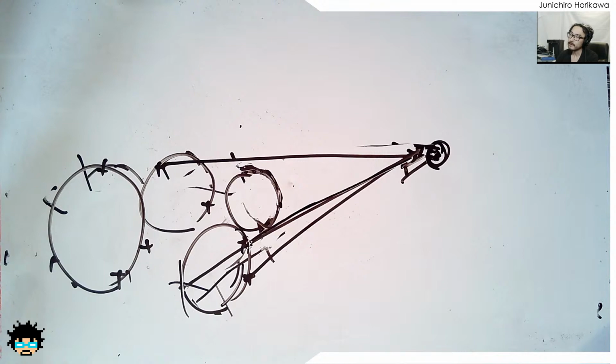Crack transform, 0, 0, which is going to be the order of the rotation and the order of the translation, scaling, and rotation. I'm going to set it to 0 as a default value, and the pivot position to be 0. What I'm going to crack is this camera matrix, and as output parameters, I'm going to output translation, rotation, and scaling.